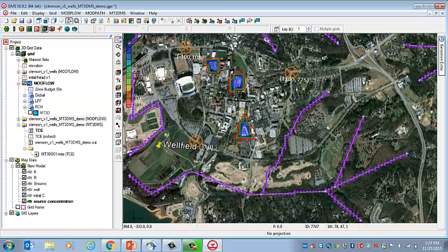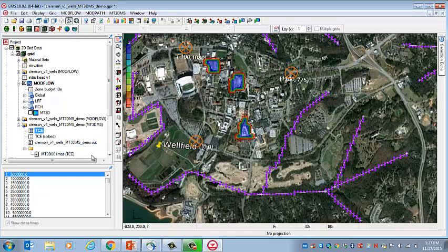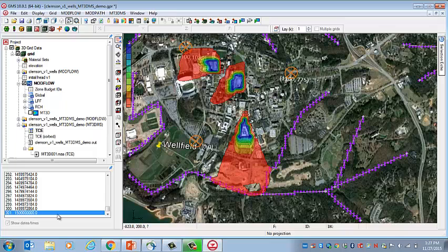All right, now we've run the simulation a bit longer, and we've got the same configuration here, but if we select TCE and scroll down, there are now 300 entries, and the last one is 1.5 times 10 to the 9th seconds. Compared to the last one, we now have the plume advancing further, and it's discharging to both this stream reach and this stream right here.